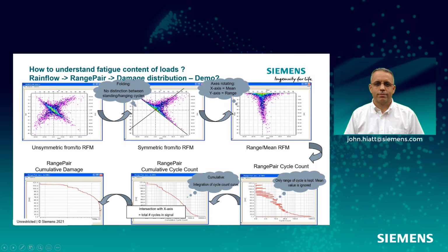This is a very important plot because it says that cycles that are below 40, or maybe you want to be a little more conservative and go 50, cycles that are above 50 create 97 or 98% of my damage. When this line goes vertical, it means that they're not really that important in fatigue. So when we do accelerated testing, part of the magic is how do I get rid of those cycles?